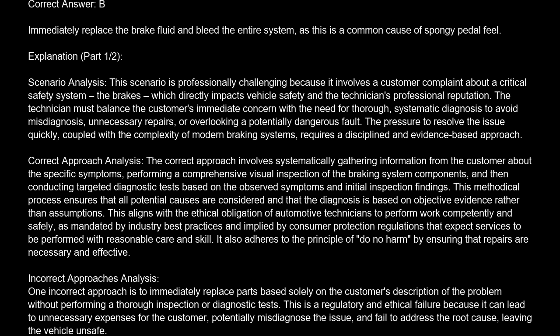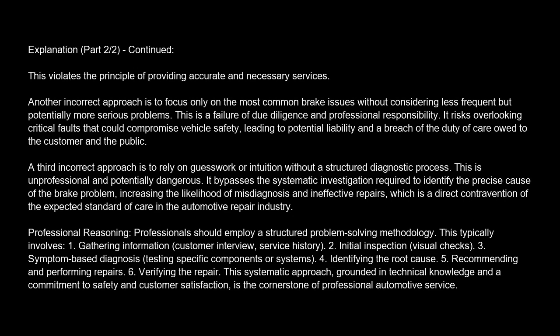Incorrect approaches analysis. One incorrect approach is to immediately replace parts based solely on the customer's description of the problem without performing a thorough inspection or diagnostic tests. This is a regulatory and ethical failure because it can lead to unnecessary expenses for the customer, potentially misdiagnose the issue, and fail to address the root cause, leaving the vehicle unsafe. This violates the principle of providing accurate and necessary services.